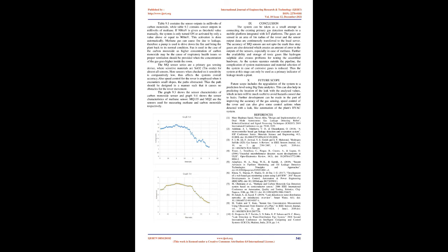Methane gas can cause fire due to leakage, therefore a pump is used to drive down the fire and bring the plant back to its normal condition. A fan is used in the case of carbon monoxide, as a higher concentration of carbon monoxide may be the cause of respiratory health issues, so proper ventilation should be provided when the concentration of the gas goes higher inside the room. The MQ sensor series are primary gas sensing devices, where the sensitive material is SnO2, tin oxide, for almost